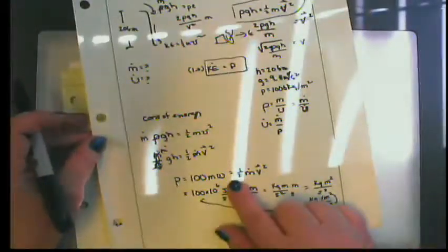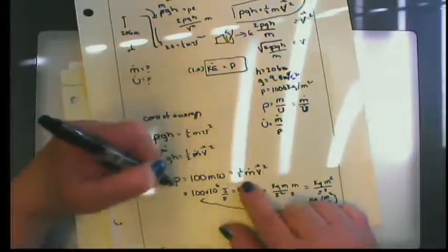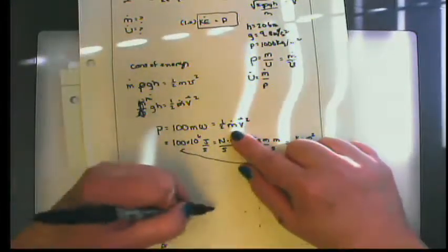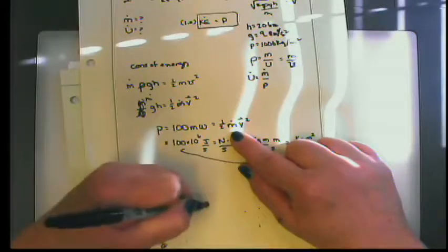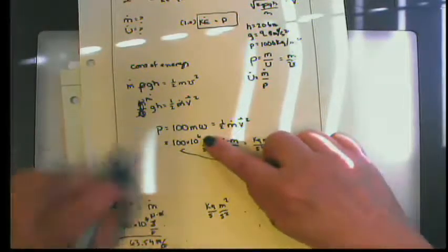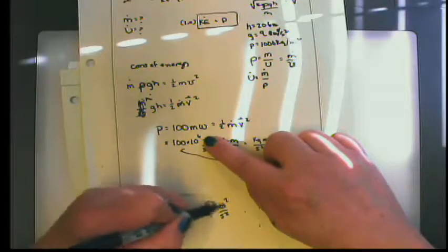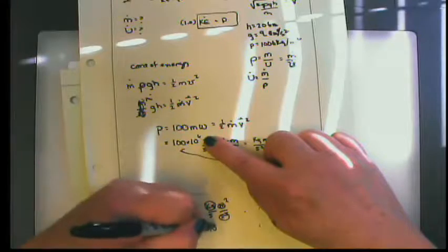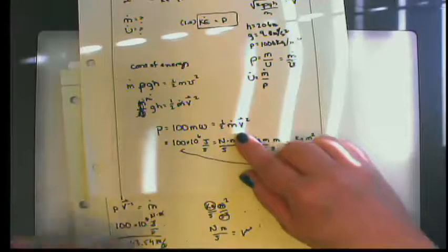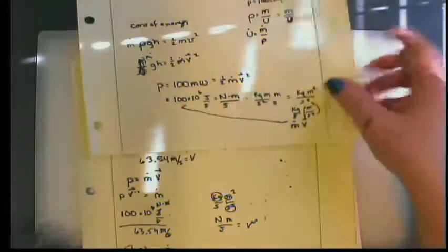Okay, so my power then, because my kinetic energy would be 1/2 mv squared, my power would be 1/2 m dot v squared. This should still work because a mass flow rate would be in units of kilogram per second, meters squared per second squared. Can I make that be a megawatt? A kilogram meter per second squared is a Newton meter per second, which is a watt. Okay, over here, kilogram per second, yeah, my units should be the same. So I have something weird in my math.